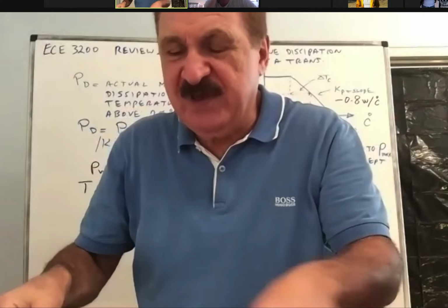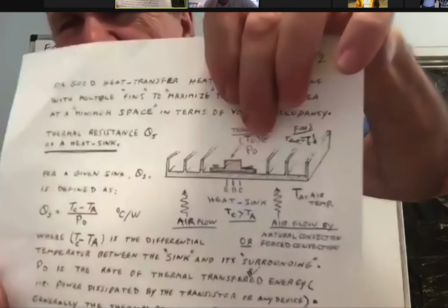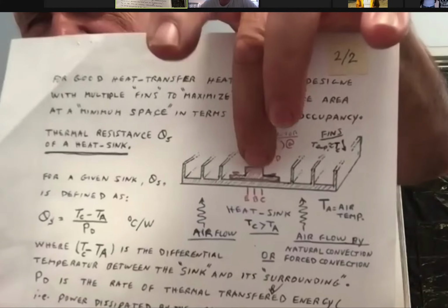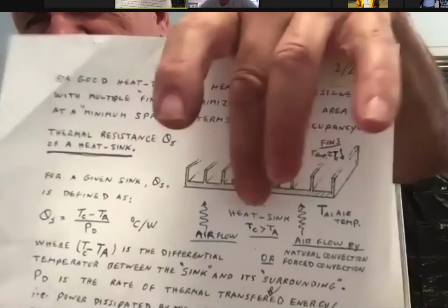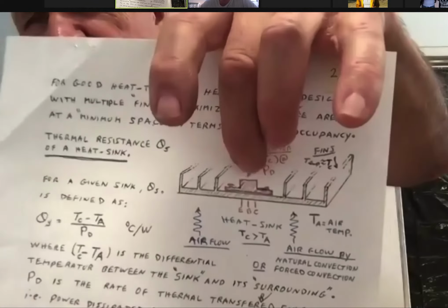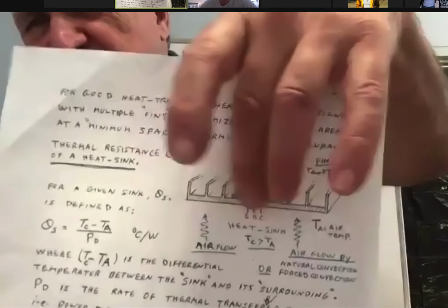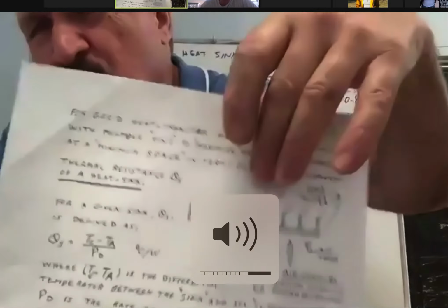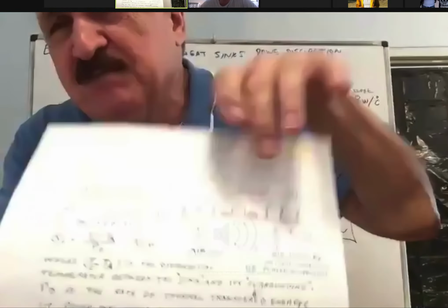So here is the picture of a heat sink, which I tried to hand sketch, with the transistor being installed in it and two wires coming out of it. There's a firm contact between the transistor and the flat part of that heat sink. The rest are fins, blades, installed on the flat plate.